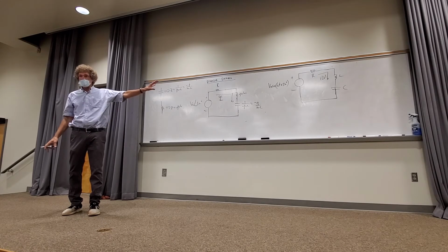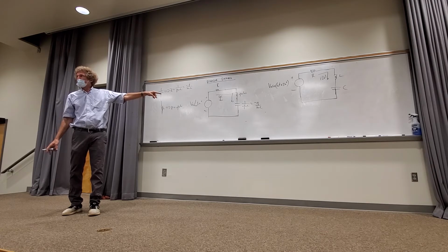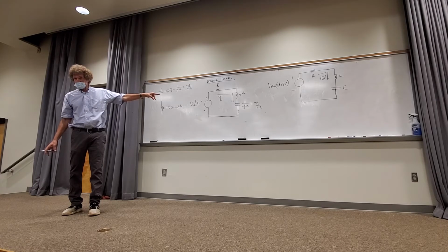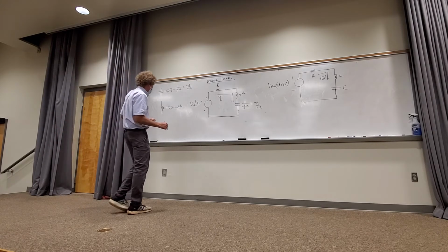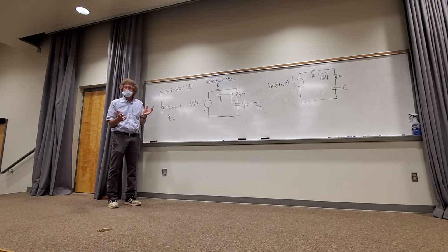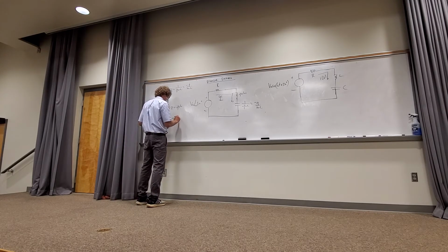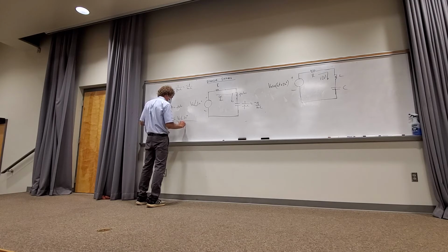Remember, you all see the transform. All you have to do with the voltage is take the magnitude of the voltage and the phase angle inside the cosine argument, right? Over here, I replaced the inductor and capacitor with its impedance value. Do you follow me? Now, when we want the current I, do it as if they were real resistances. If we had a voltage right there and you wanted the current, do you see they're in series? What would you do? You would take V naught at an angle of 30 degrees, and you would divide it by R plus j omega L.